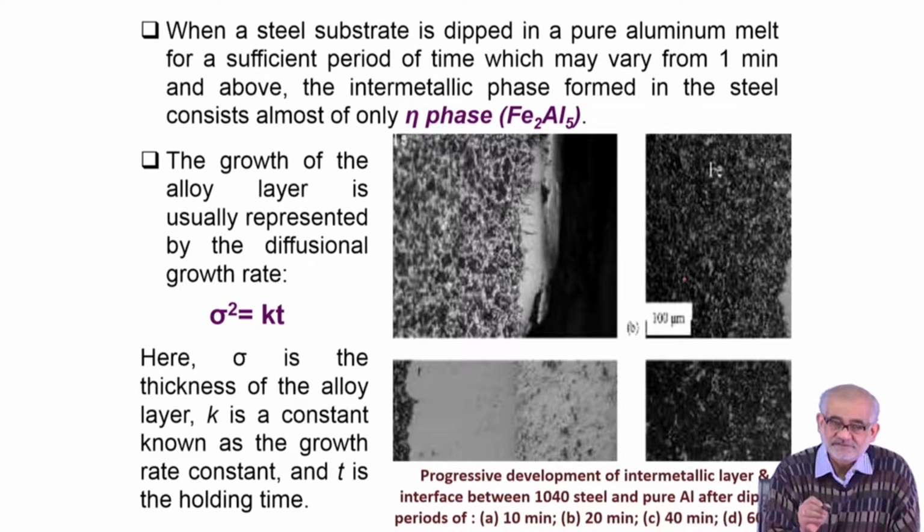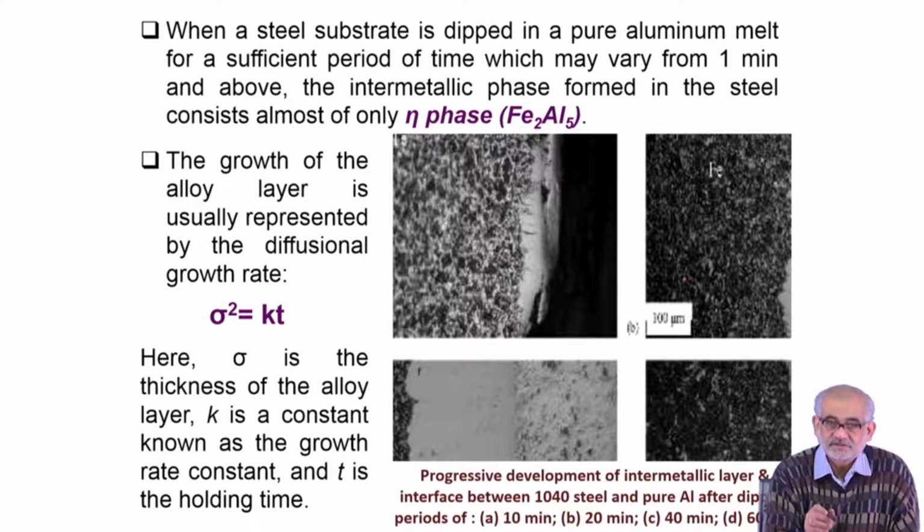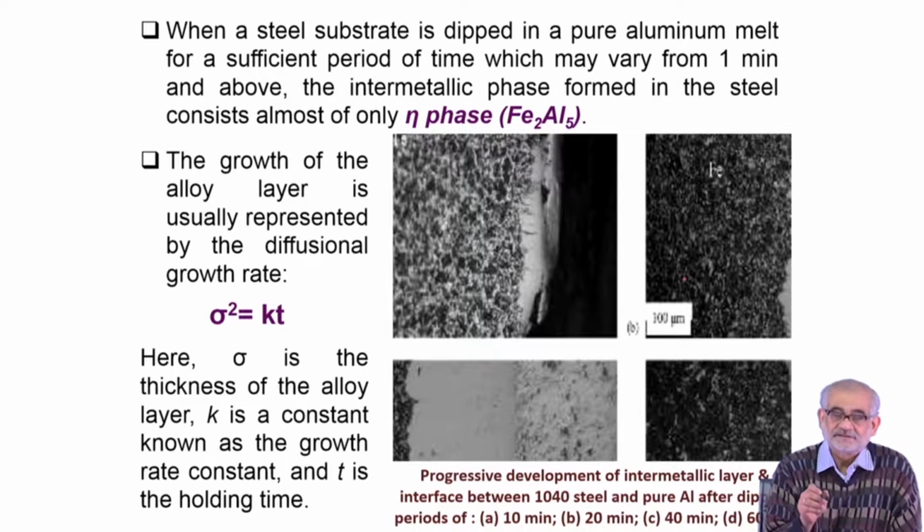The surface is an alloyed layer which will have higher concentration of aluminum or chromium or silicon, confined to a thin layer, but they do not necessarily form only a solid solution of aluminum in iron or nickel or titanium.